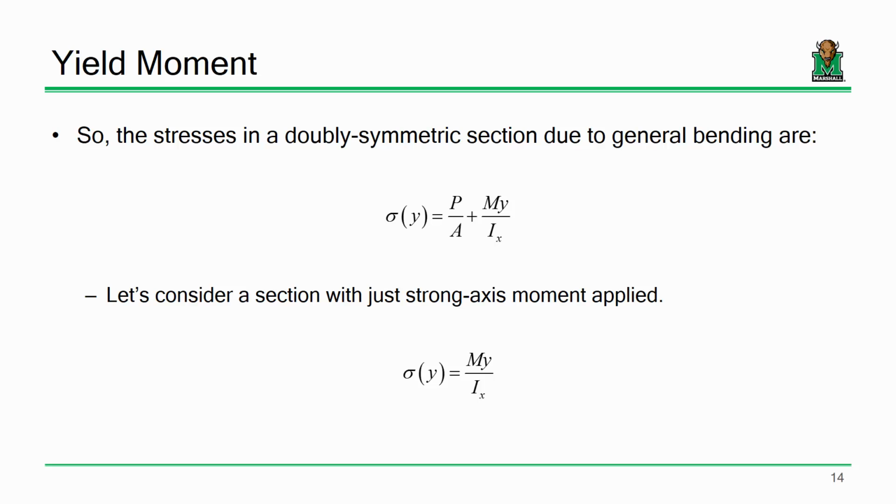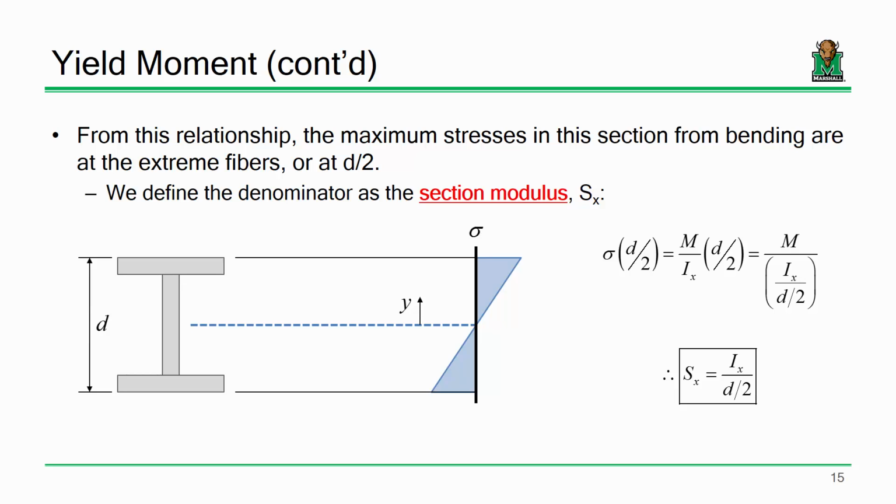Okay. Now, if we're only considering bending stress, we've got sigma equals My over I. Fundamental basic bending stress formula. Okay, now, right off the bat, we should see some quantities that we should be very familiar with in this course. I mean, sigma equals My over I, I being that moment of inertia. If you can't compute the moment of inertia of an I-beam by now, especially after homework 1, where we developed this massive Excel spreadsheet to do that for us, you'd probably be in some trouble. But by now, we should be pretty good on that. So far, so good? All right.